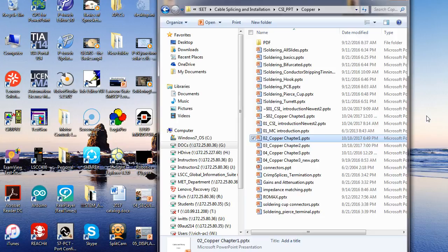Then after that, we're going to start terminating some copper wire. We'll look at methods of terminating the wire. We're going to deal with soldering. We're going to show you how to splice and terminate using solder, which is in my opinion the best way, if you do it right, to splice or terminate electrical conduction. Then we'll let y'all do that. Then we've got crimp splices, and a combination of crimp and solder splices that we'll look at. We're going to show you how to wire a wall plug up, and how to wire Ethernet connectors, wired Ethernet.